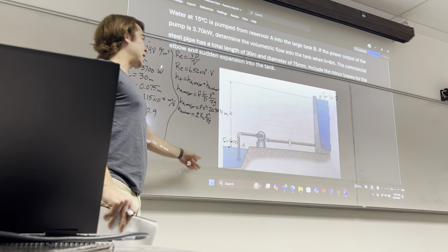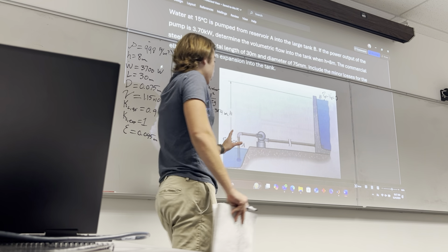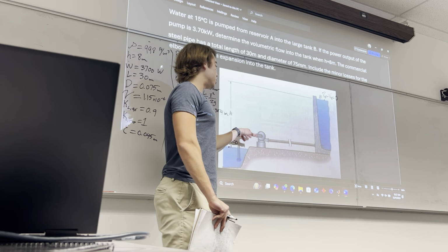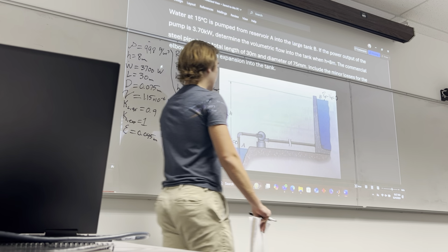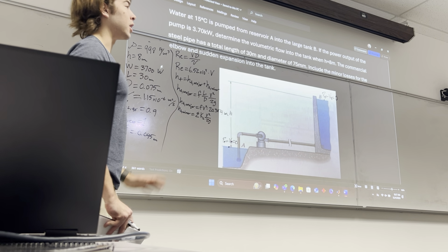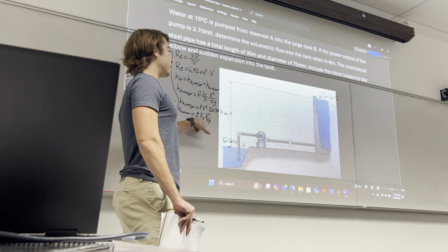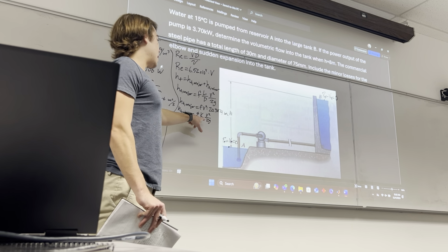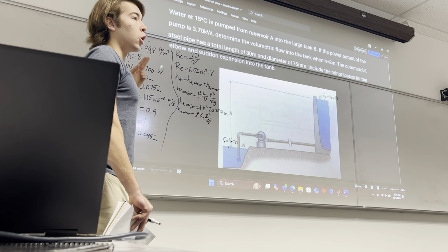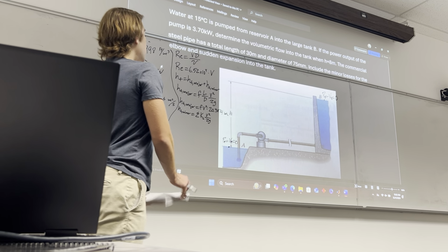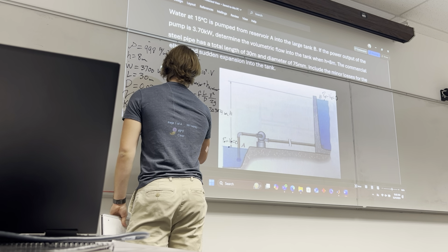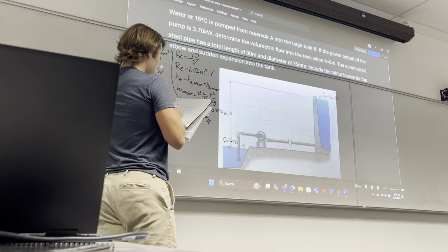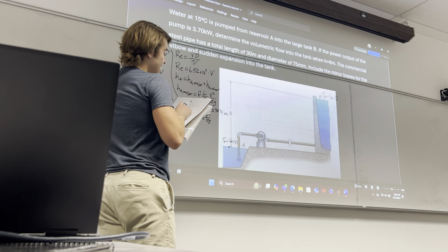In this case, this V squared is the velocity inside the pipe. At V_A and V_B it's 0, but obviously there's some velocity inside the pipe, and we're going to assume that's constant. We're not going to be fiddling with the velocity inside there. So velocity is the same, and gravity is obviously the same. Inside this sum, I would just call this 1.9. I'd add the coefficients together and then do normal math from there. So adding everything up, the h_f minor equals 0.09684 V squared.